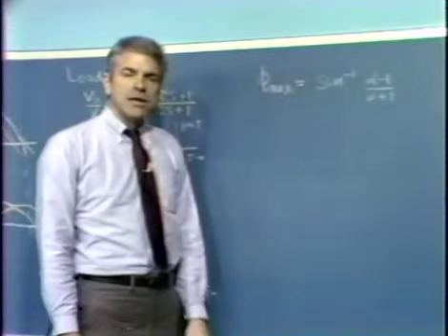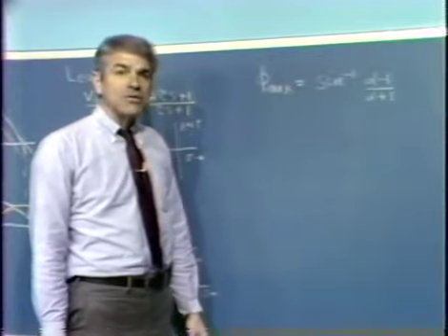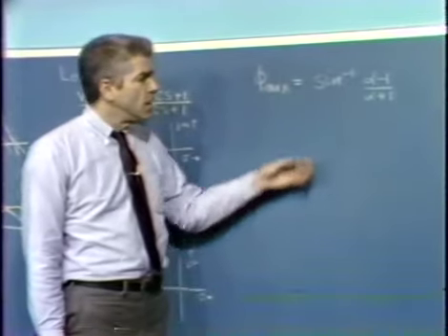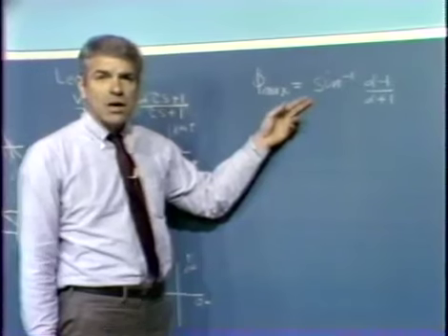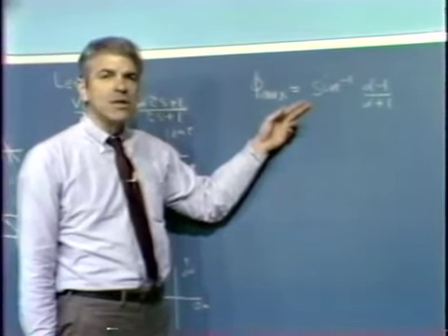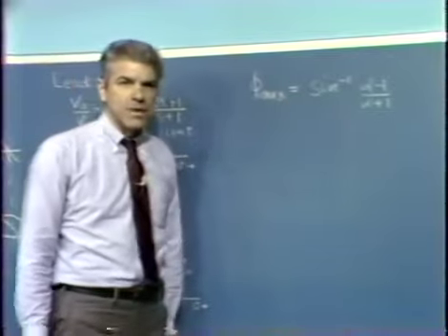We also recognize that we have to have more degrees of freedom than simply adding these transfer functions. Very frequently, we combine a lead or a lag type transfer function with a modification to the A0 F0 product. And that combination is a very, very powerful way to improve or to modify the performance of a feedback system.